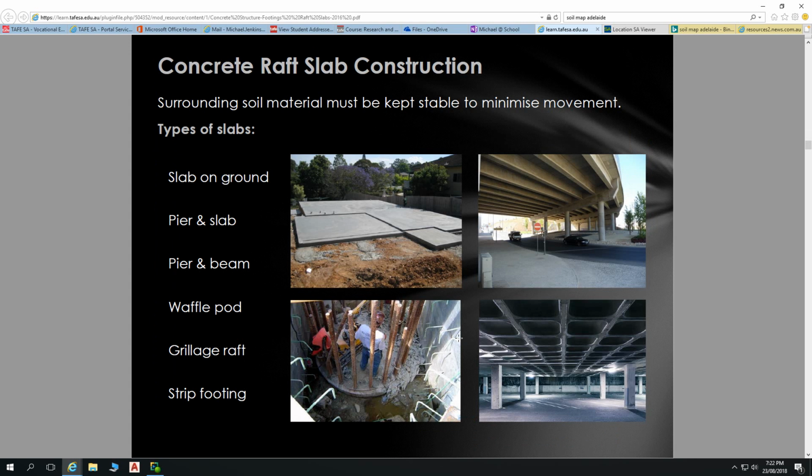Yeah. So it's the big styrofoam box, and you just build it on a flat site. So you don't do any excavation for beams. You just level out your site like this floor. You set your styrofoam boxes out. You do your edge form work. Put the steel bars in, and then you pour the concrete over the top.